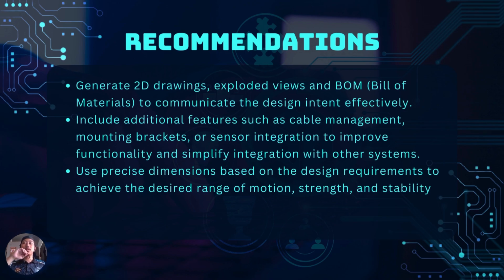So next, we continue on the recommendations. Here are some of the recommendations that can improve our design of robotic arms. The first one is to generate 2D drawings, exploded views, and BOM, which is bill of materials, to communicate the design intent effectively. Second is to include additional features such as cable management, mounting brackets, or sensor integration in order to improve the functionality and simplify integration with other systems.